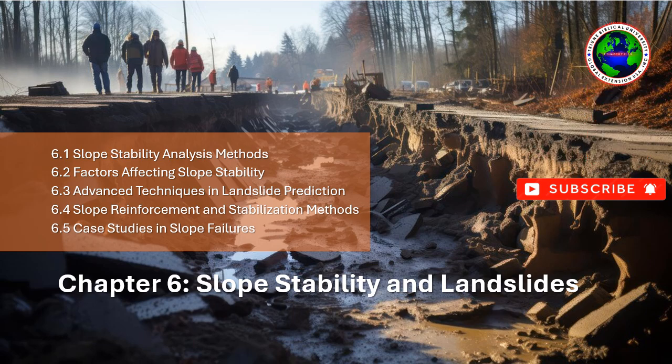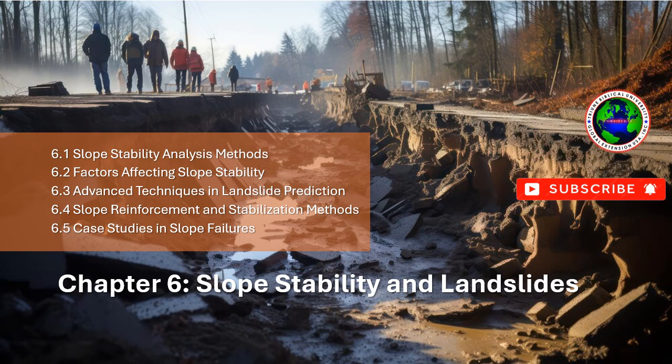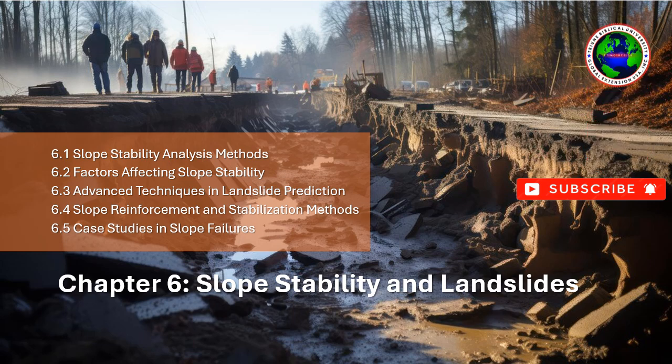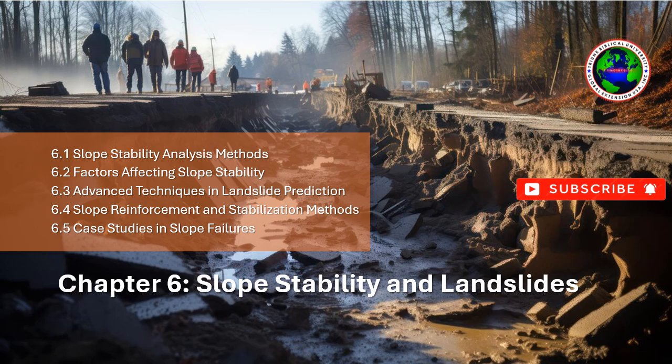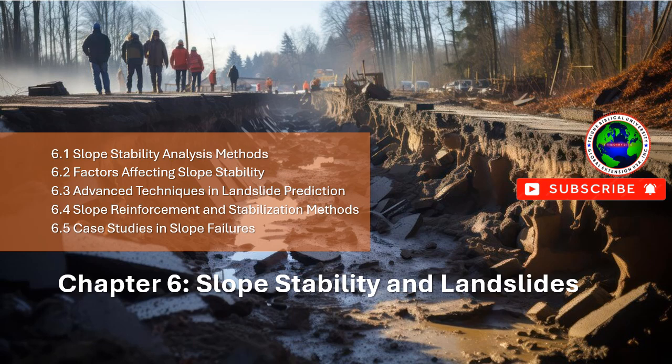SRM involves reducing the soil shear strength, either cohesion or friction, incrementally, and monitoring when the slope reaches failure. This method directly evaluates the strength of the slope and does not rely on pre-defined failure surfaces. Nonlinear analysis. SRM can account for the nonlinear behavior of soil, which is particularly useful for soils that exhibit stress-dependent strength behavior.